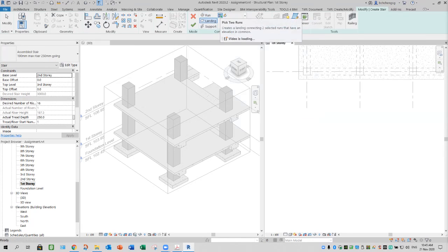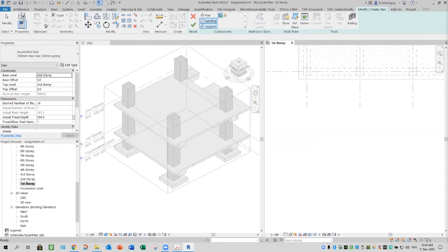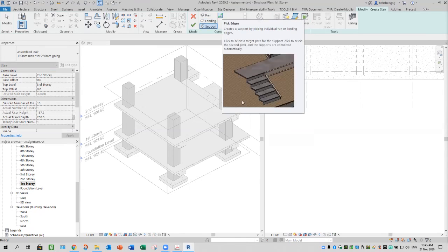Look at the video. Yeah. So you can see that the staircase breaks into 3 components: the stair flight, the landing, and the support. Support, in the architectural world, they call a stringer. So a stringer, you can have interior, exterior, and so on. This is more towards your exterior. And you can see that it's more like a channel on the steel structure.